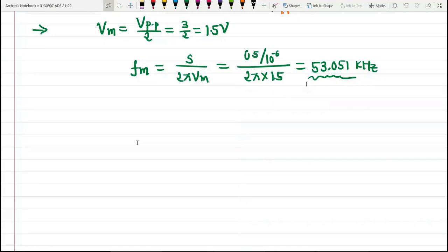Then what will happen? Then the two base currents will be different, and there is some difference between their base emitter voltages also. And due to this, what happens? The presence of unwanted voltages and currents will be there, and these unwanted voltages and currents are called offset voltages and currents.